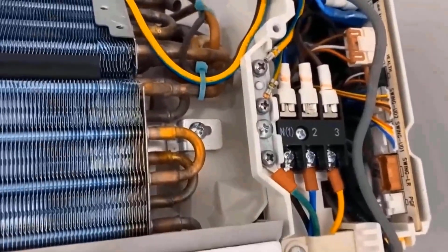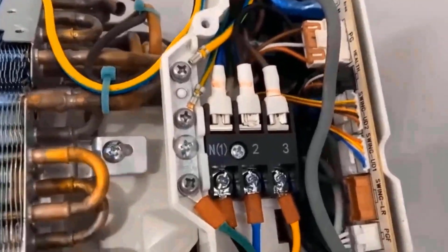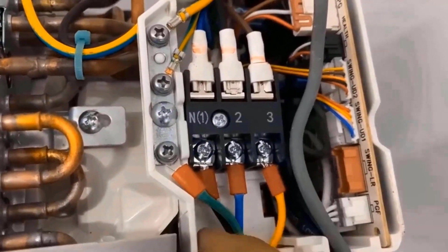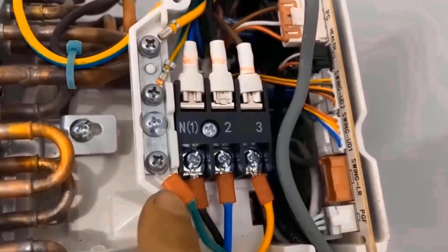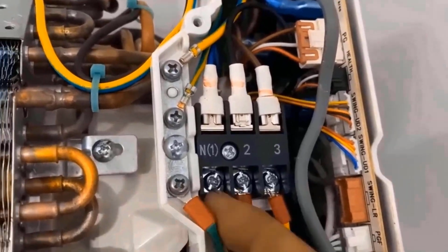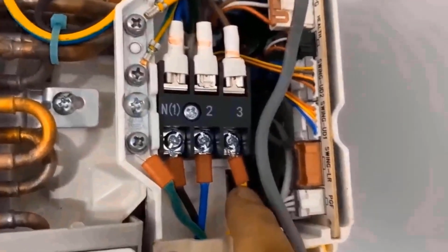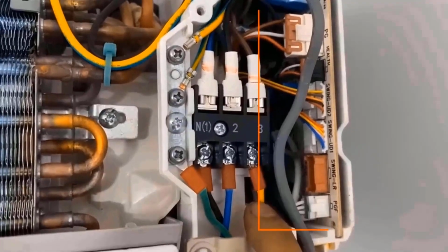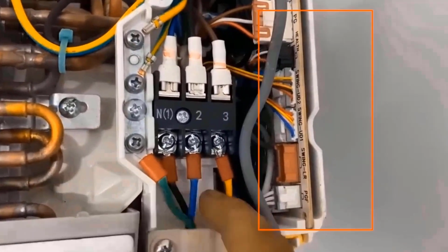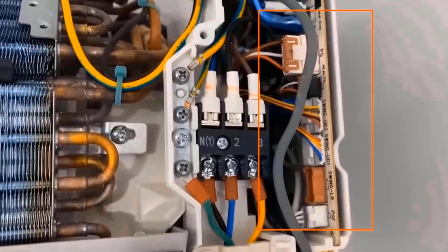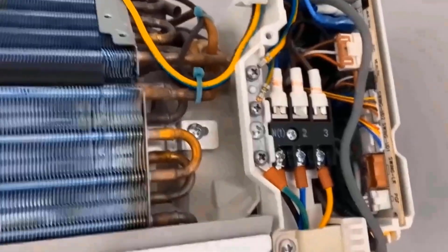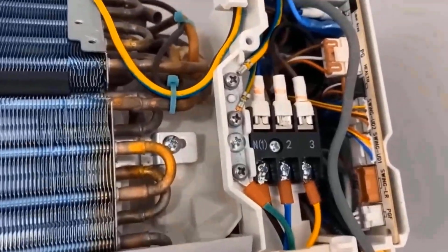Over time, due to humidity and environmental conditions, oxidation can occur on the internal pins that make contact with the pins on the board. This oxidation can compromise the passage of electrical microcurrents, resulting in communication or electrical failures. To check, remove the connectors from the board, use a contact cleaner to ensure everything is clean, and reconnect several times to eliminate the oxidation and ensure good contact.